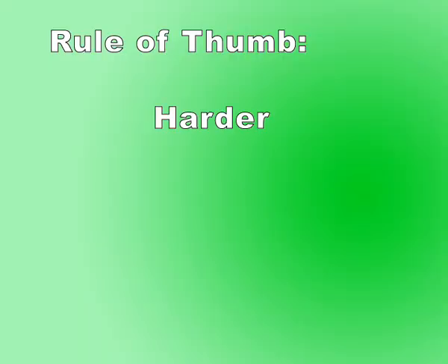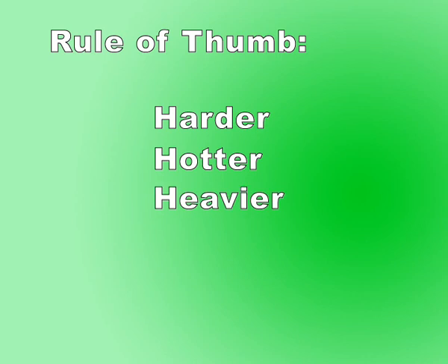So the harder we're pulling product, the hotter the tower gets, the heavier the end product at the overhead will be.